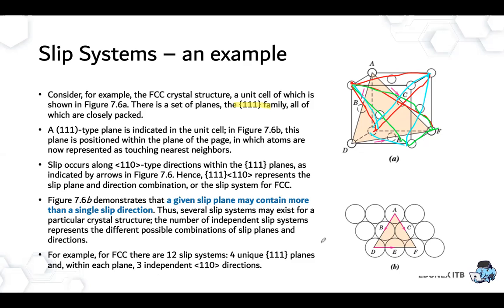Okay, so all of the dislocation will just occur on those slip planes. That means the more slip systems a metal has based on the crystal structure, the more likely it is to have dislocation. If there is more dislocation, that means the metal is easier to plastically deform, and if the metal is easier to plastically deform, then the metal is going to be more ductile.